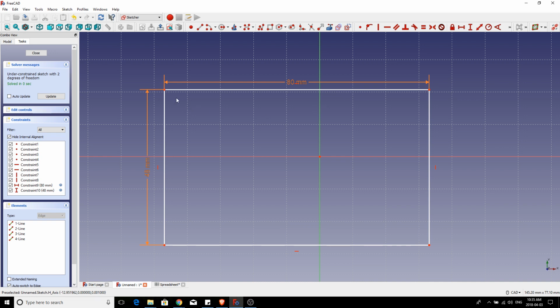What it means is that if we select a couple of points and then we specify an axis that we want to apply symmetry to, it will make sure that those points have an equal amount of space between them and the axis on both sides, even if it means moving the model. Now, once it does that, the CAD program is able to calculate the X and Y positions, and it gets rid of that under constrained sketch message that we're seeing over here.